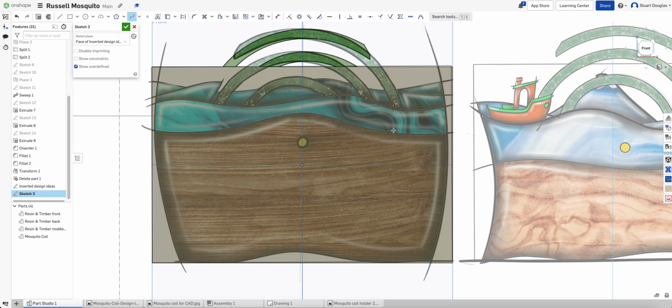You can see on my sketch this is what it is, so I'm only interested in this line at the moment. So I'm going to sketch, and I'm going to try and do this with as few points as I can to get a smoother curve. And notice that my line starts and finishes outside of my shape. I'm going to press Escape to stop sketching.